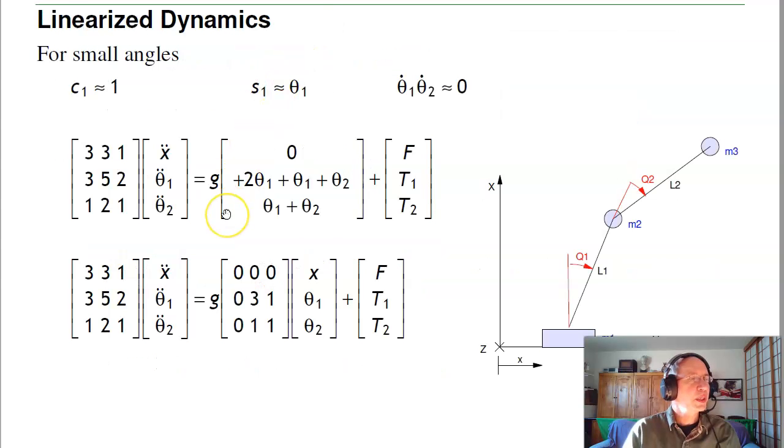So here's a question for you. What are the eigenvalues? Again, eigenvalues only apply to linear systems. This is nonlinear. So to linearize it, I need to pick my operating point. In this case, it can be either straight up or straight down. Find the linearized dynamics at that operating point. If I have it pointing straight up, then here's your mass matrix. Here's the gravity matrix. The Coriolis force matrix has all these higher order terms that are roughly 0. Then the generalized input.